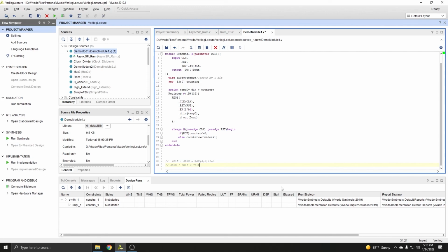As well as I recommend you, when you're writing any Verilog module, to always, regardless of how simple it is, especially when you're learning, always create a test bench for every module. Just test bench every module. Because if all of your modules work, and then there's an issue when you put them together, you know the issue is not in the modules, it's an issue with how you put them together. So you eliminate the issues within the modules first.